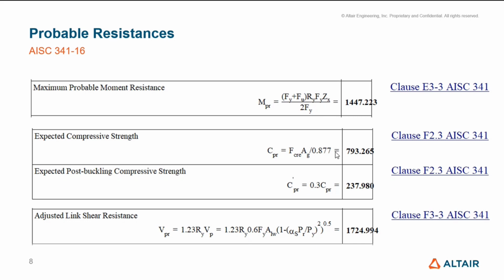So this information can be used in the analysis model when performing a nonlinear analysis in S-Frame, which is required to determine the design forces for the non-yielding members, or in Canada we call them capacity protected members. Recall those members that we don't want to yield based on the capacity design principle. And let's look at how this works in S-Frame.